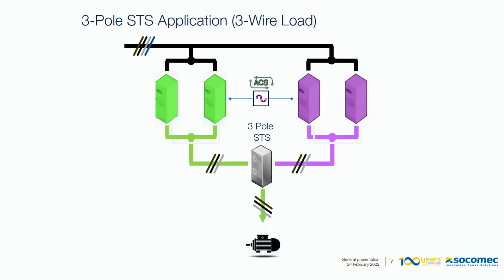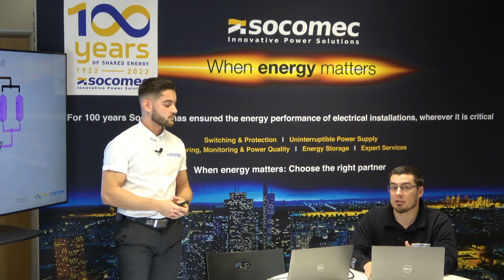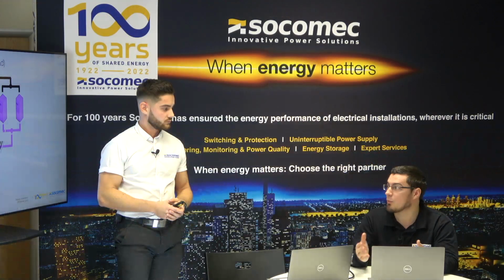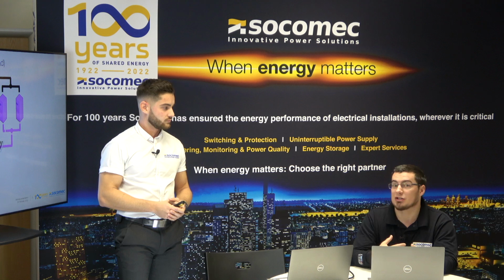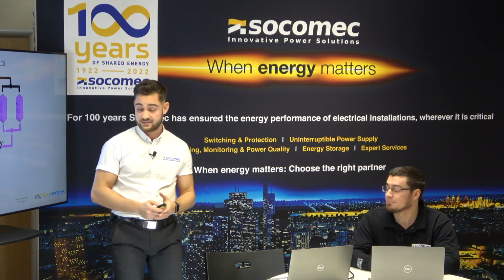Just to pick up there on the motor load: if we know that most of the load is a motor-based load, then we have a particular setting within the STS that we input when we commission, so that we can manage the load better and make sure that any regenerative current when you're doing that transfer is managed by the static switch, and you don't get, again, nuisance tripping of the input supplies. Correct.